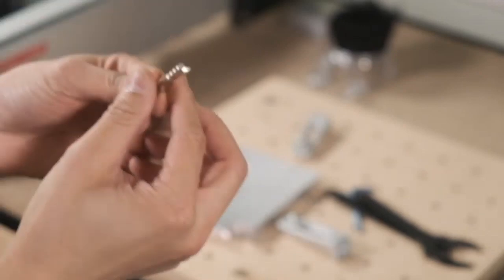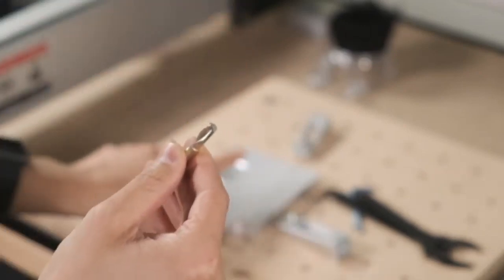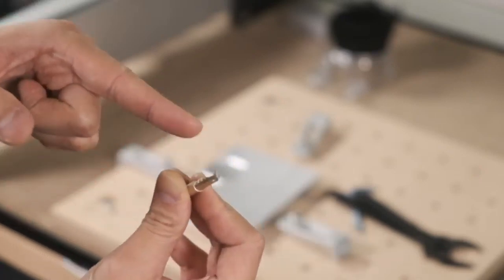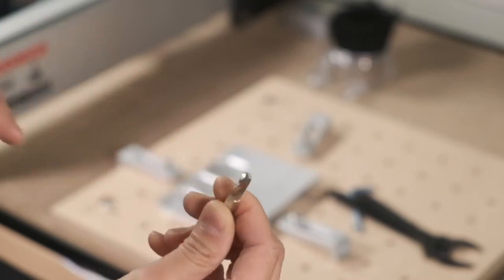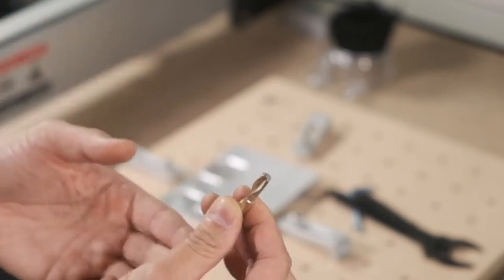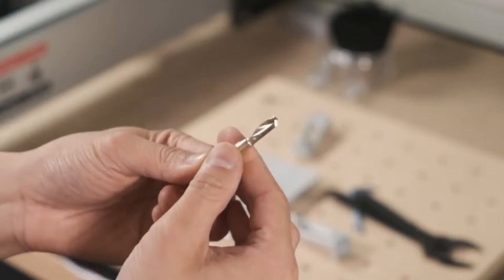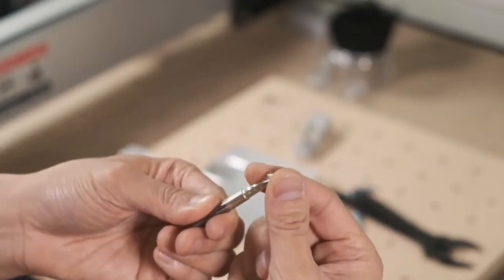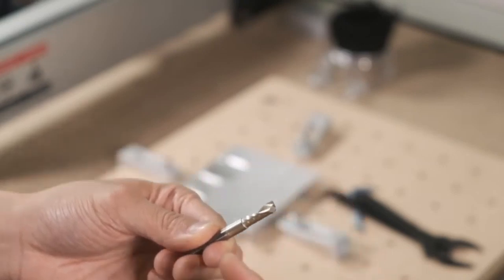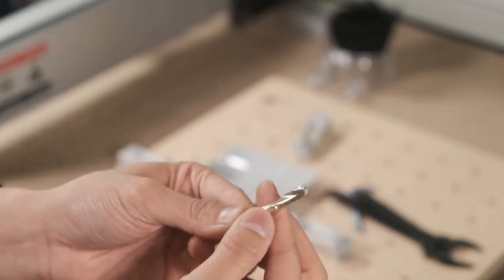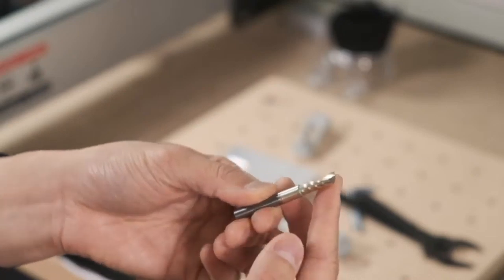But the faster an end mill spinning, the more times per second it's going to hit your stock. So a 3-flute end mill is going to be impacting 3 times per revolution. It's going to, in theory, take 3 times the amount of torque for the same RPM. So single flutes let you hit the material really fast while putting the minimal amount of force back into your machine. So that is the 278Z.